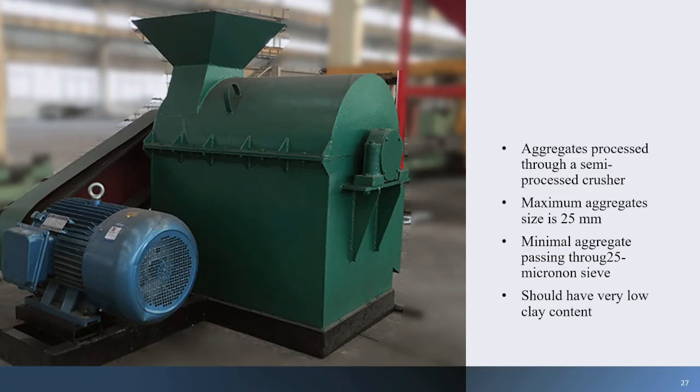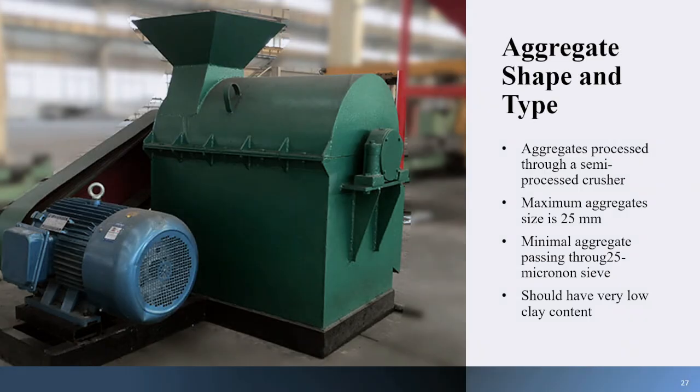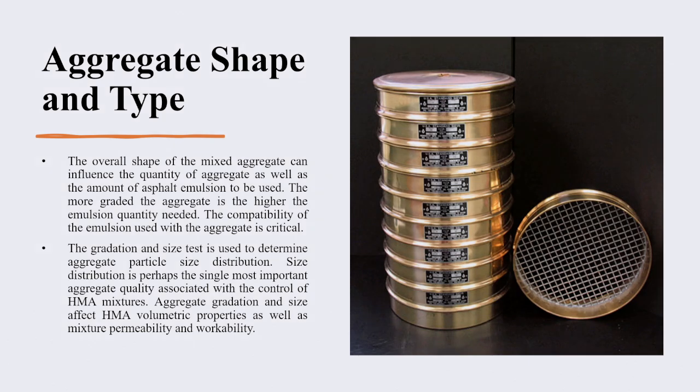And I always mention this because I do teach concrete and I do teach soils, and I do teach asphalt, everything relevant to materials. And basically, when I teach concrete, when I talk about the aggregate, do you remember what sieve separates between coarse and fine? You know, sieves, you either classify the sieve by the size, like when you say 1 inch, it means the net opening is 1 inch, or 25.4 millimeter.